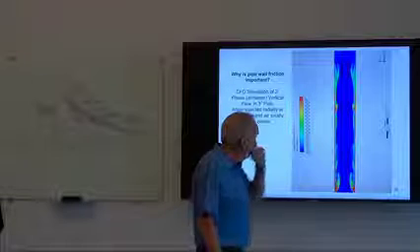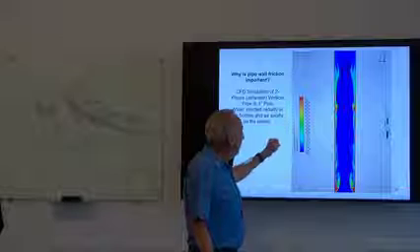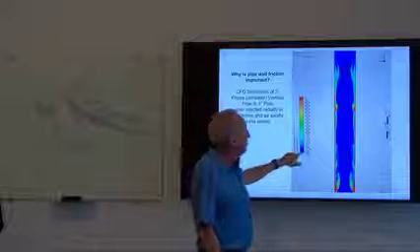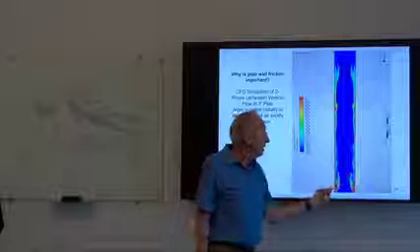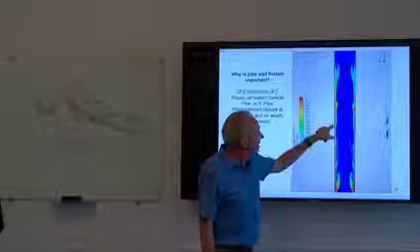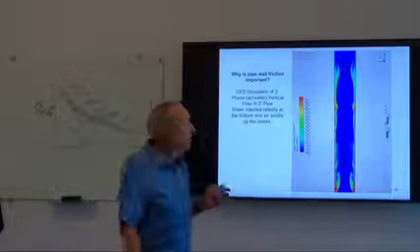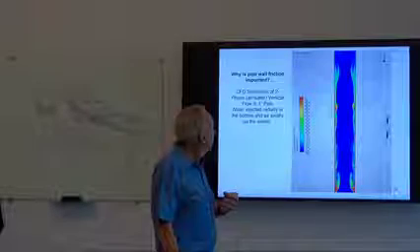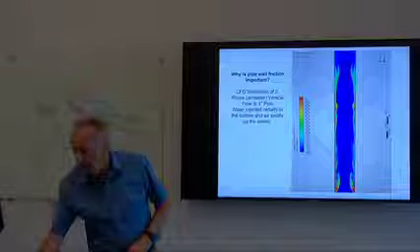And these are liquid volumetric fraction. So blue is low, means it's mostly gas, there's very little liquid. Red, we see here on the tubing wall, is a high liquid fraction. It's mostly liquid. In this case, I think they did it with water. Yes, it was an air-water mixture.